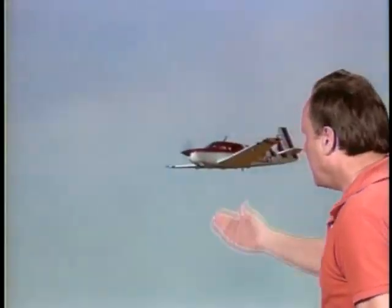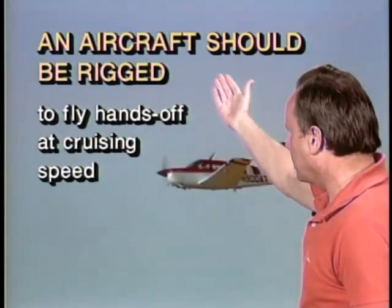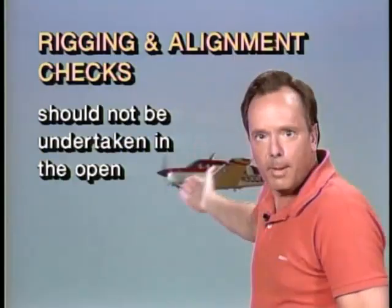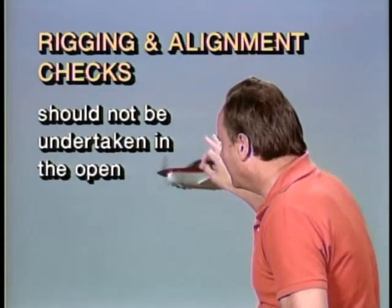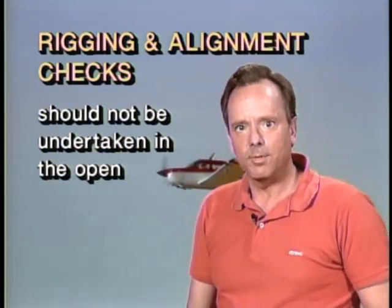Now let's talk about aircraft rigging and rigging checks. An aircraft should be rigged to fly in a hands-off condition in cruise. So you want the airplane to be able to fly hands-off at cruising speed. Rigging and alignment checks should be undertaken in the open, and that would be by far the best thing to do. However, if this cannot be avoided, the aircraft should be positioned with the nose into the wind, so the wind is minimized as a factor in the rigging and alignment of the aircraft.